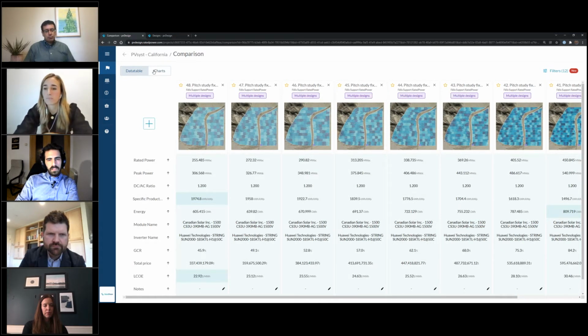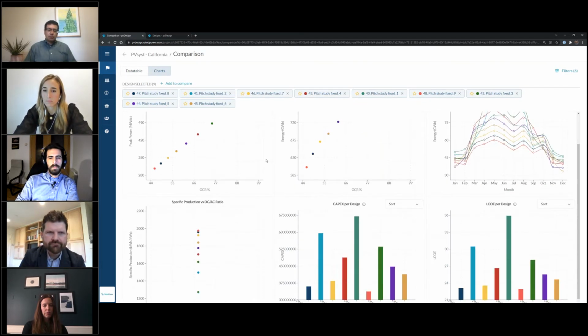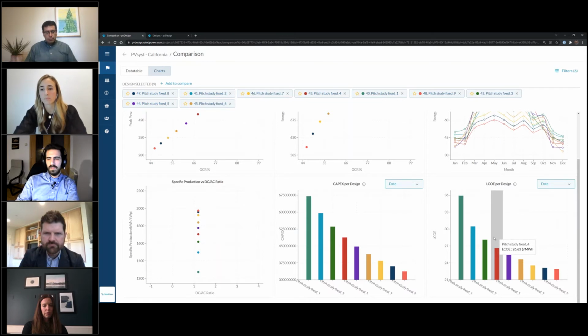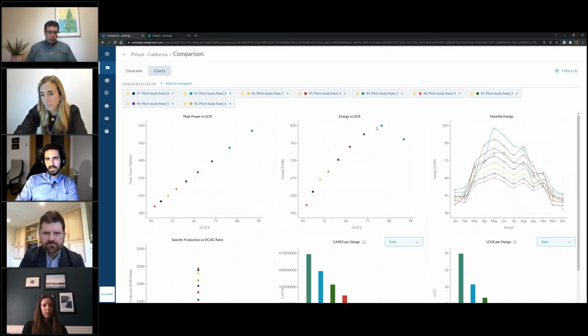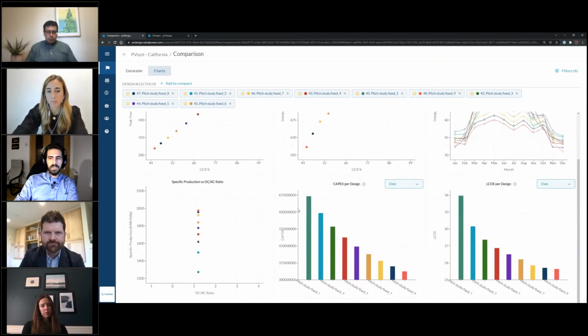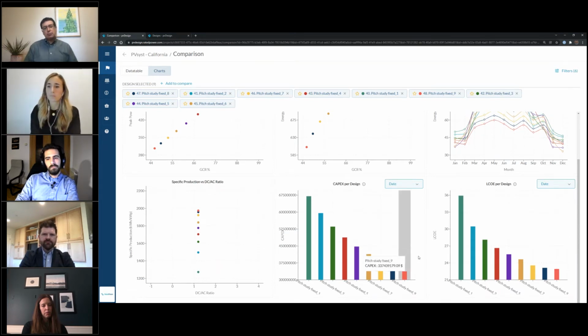And if you include the economical analysis, so if you include your costs into the simulation, you can review the capex and the LCOE of the designs and find the optimum. And here, as you can see, there is a trade-off between efficiency and the production, right? We have more production when the pitch is very close, but then as the year goes by and you get into winter, you start getting lower production because of shading losses. With this tool, you can really make an in-depth analysis from the get-go regarding that part of the engineering process, which is usually very hard to do so thoroughly as what you can do with pvDesign.